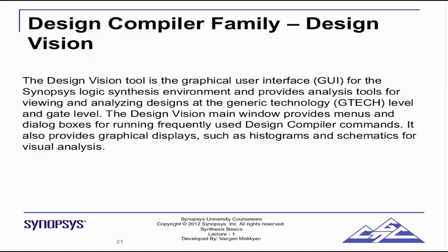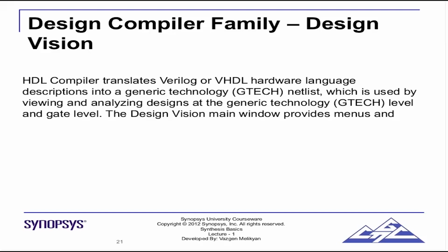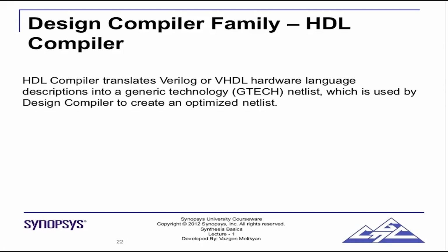It will be much more intuitive than the graphical user interface. As you start practicing on this, you will see the reason why. There's a feature called HDL compiler. The HDL compiler translates your Verilog and VHDL into GTECH. So again, this HDL compiler is very much like a Verilog compiler, what you might be using in your other course. For example, NC Verilog; this HDL compiler has a lot of those features. That's what it does. Now your Verilog code will not be the same.